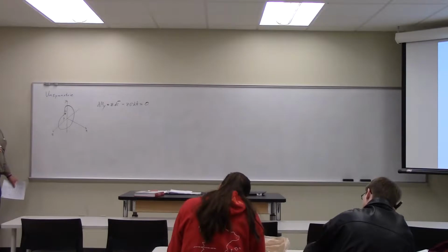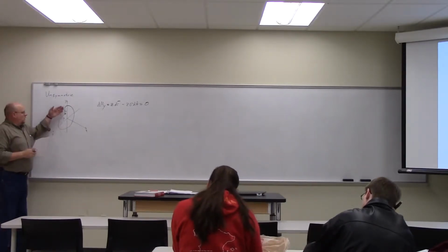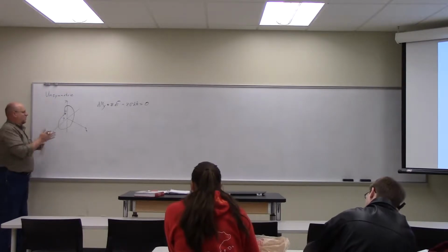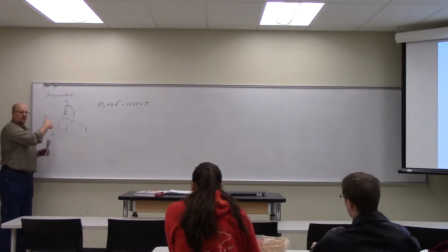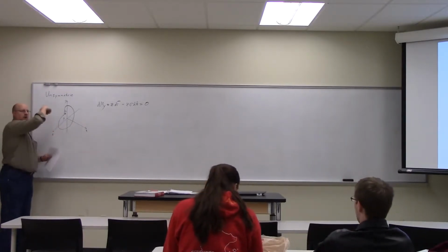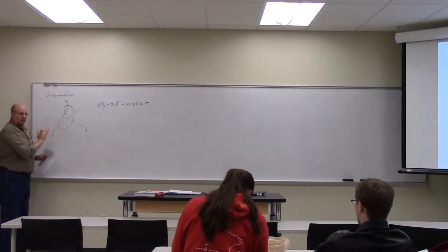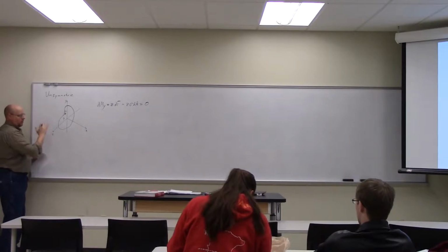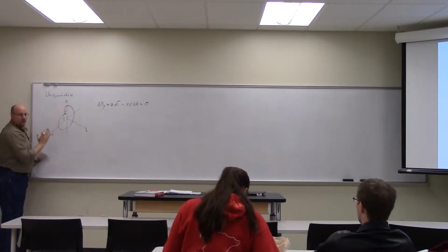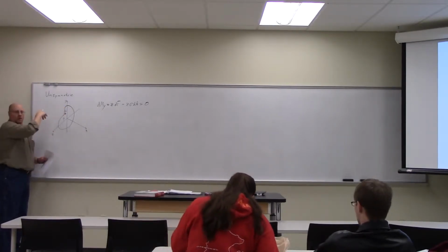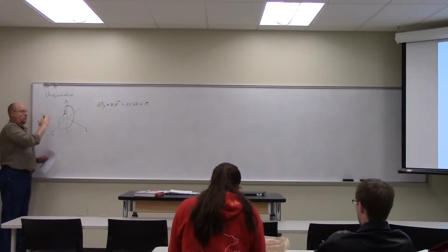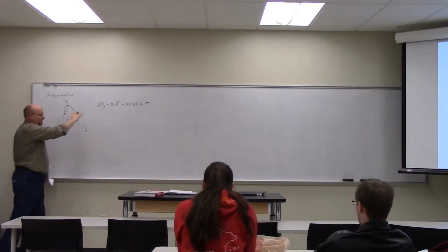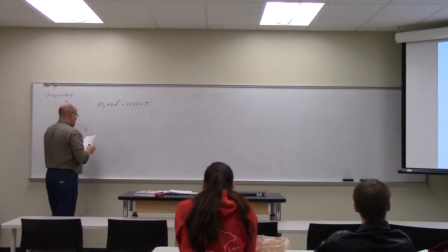We can have no net moment about the y-axis if we want it to bend purely about the z. Because if there's some moment about the y, it's going to bend off in some wonky way, even when we apply a direct z moment. So we have to get that piece to equal 0.